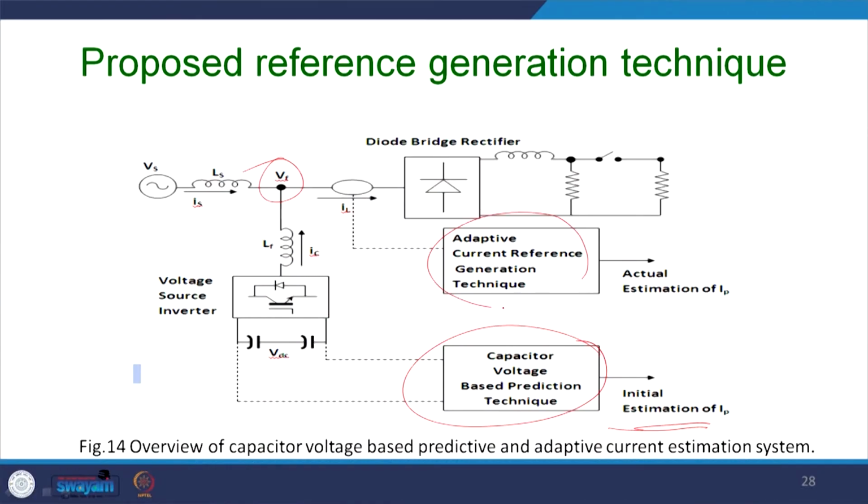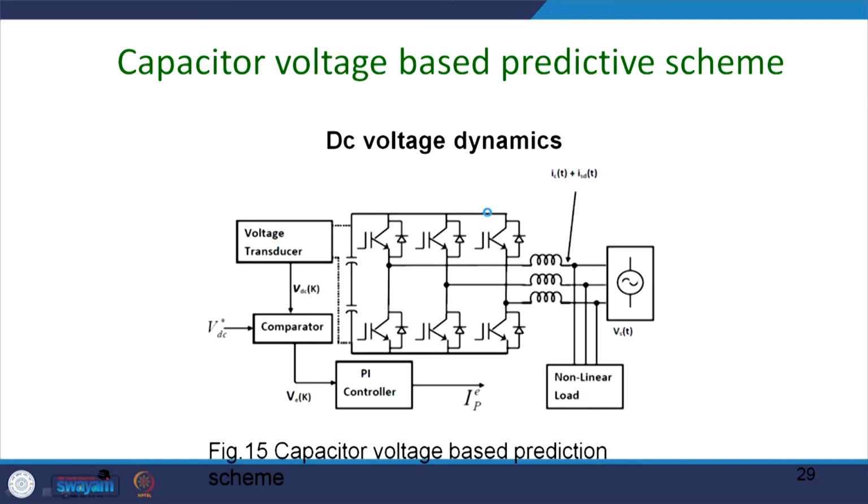But the direct method cannot bring the value of THD down quite satisfactorily, because everything is put on this filter, and there will be a tuning done by the adaptive filter to give you accurate results. So, this is a predictive adaptive combination of the NN that gives you better results. I can show you the results of the simulation as well as the hardware.